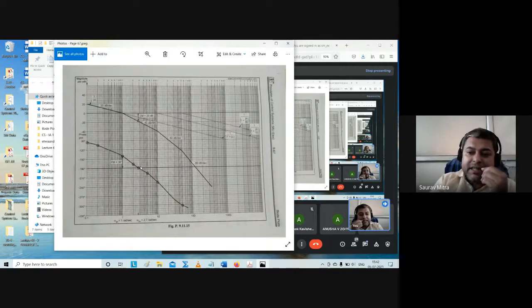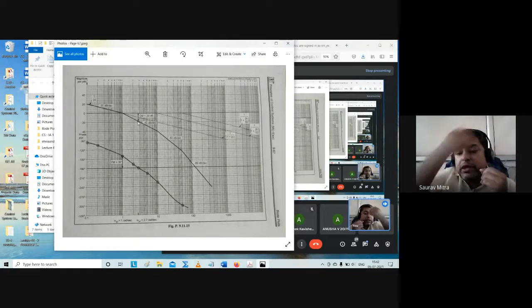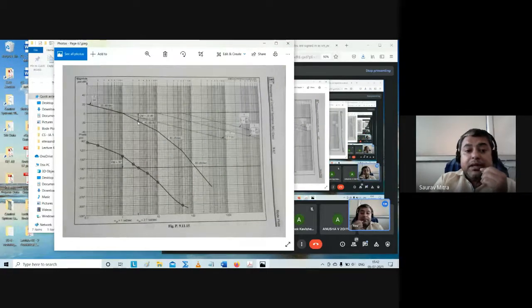And we are finding graphically by sketch that the phase is crossing the minus 180 degree line at 2.7 radian per second, and that frequency we have taken up. How much is the gain at omega pc? We are finding that it is around minus 20. That means we still have a plus 20 dB cushion. We can still increase the gain by 20 dB and still get a stable system. So gain margin is plus 20, phase margin is plus 36. Hence, both gain margin and phase margin are positive. The system is stable.